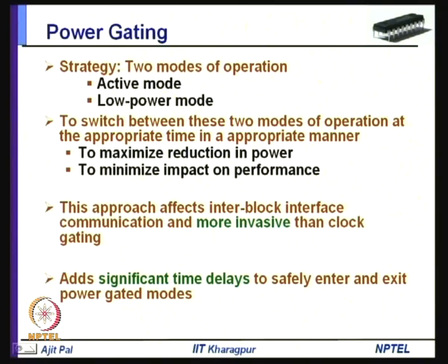But in this particular case, as we shall see, it will affect the timing and all the characteristics of the circuit. As a consequence, it is more invasive than clock gating, and it will add significant time delays, and we have to see how to safely enter and exit power gated mode. So, there are significant time delays to safely enter and exit power gating modes.